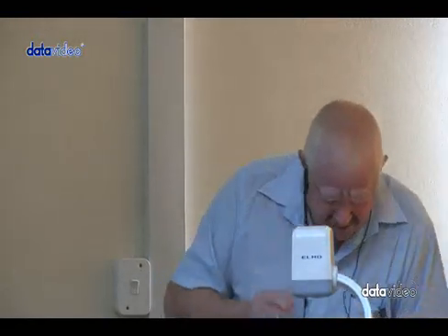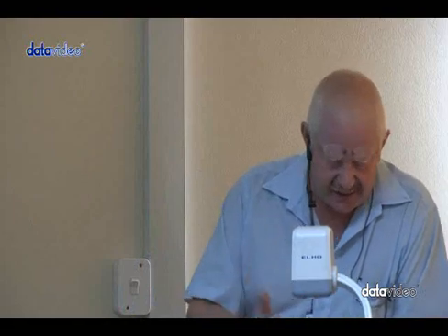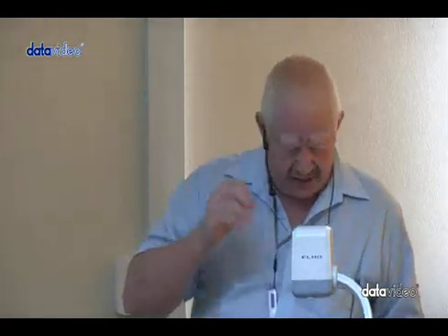Five r parameters commonly used for BJTs are given there in table 6.1. Now alpha and beta you are familiar with. You have done them under DC, but these are the AC quantities if you look at the lowercase subscripts. Alpha AC is still the ratio between collector current and emitter current. Beta AC is still just a ratio, no unit, between collector current and base current. The new ones introduced here, however, are the AC emitter resistance, the AC base resistance, and the AC collector resistance, indicated r'e, r'b, r'c.